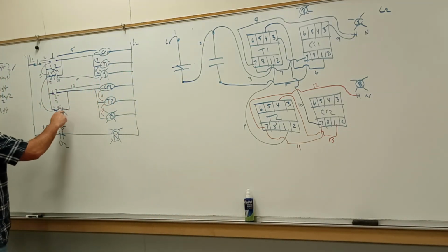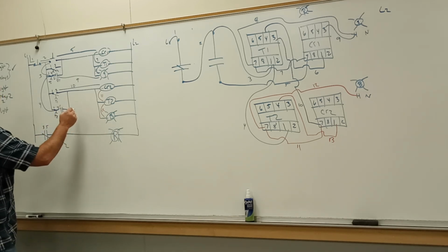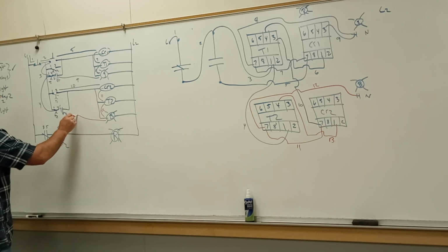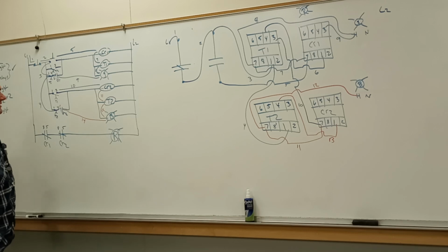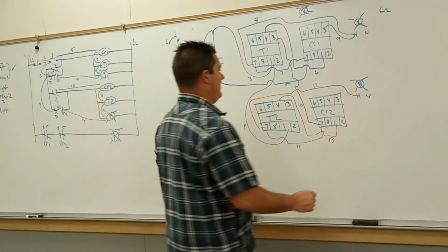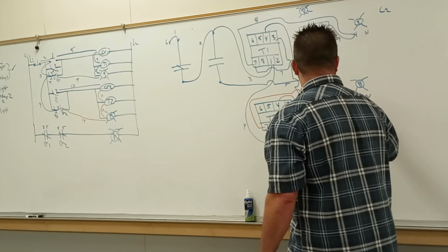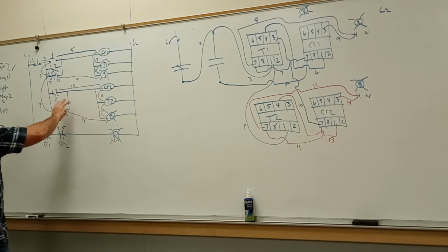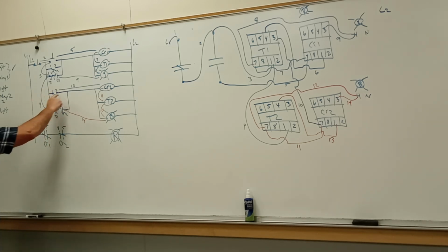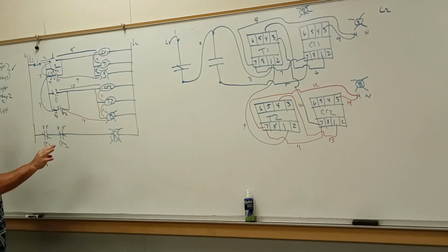Got to seal my memory right here. You can take it from blue light to the memory seal, number 14. So blue light to memory seal, wire number 14.